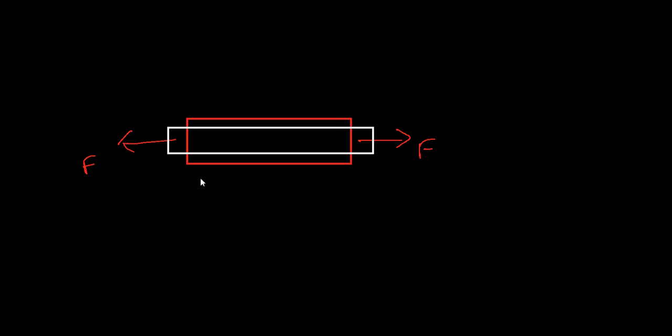So the stress generated will be the same unless there is a restriction or prevention applied for the deformation in the lateral dimension.